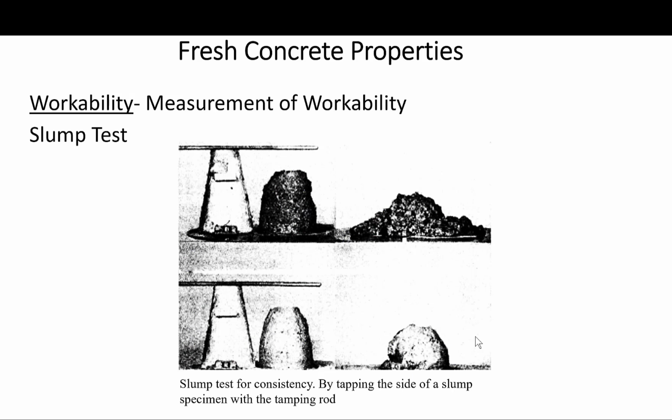So you must be careful when evaluating the slump test results. An experienced person should evaluate the test results, meaning not just filling the cone and rodding, but being able to make a decision on accepting or rejecting the concrete, or at least to escalate the issue to their supervisor to make the decision. Any changes are almost always indicative of something that has been changed, and attention is required.